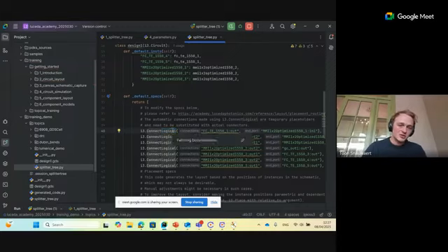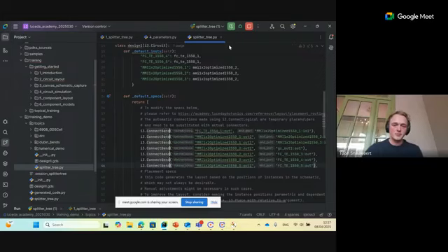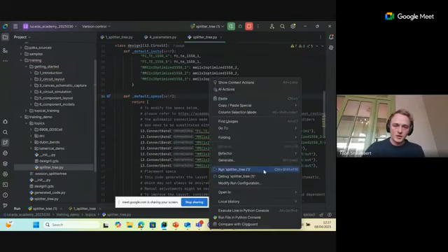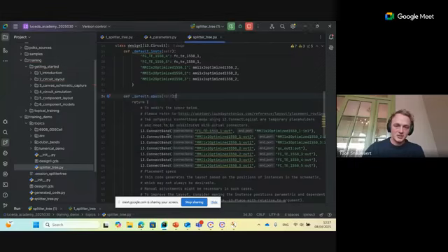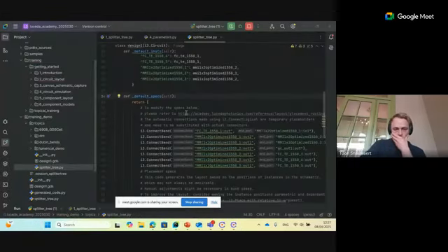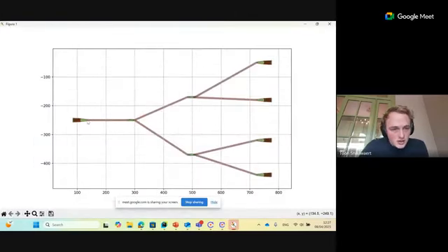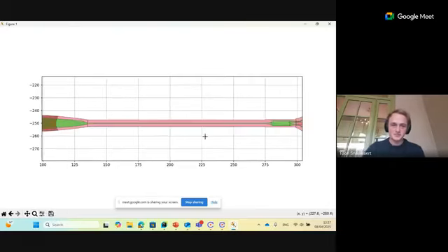What we want to do is we want to create waveguides, so we can change this to the Connect Bend or the Connect Manhattan. If we run this now, we can see that now between the components, we have actual physical waveguides.